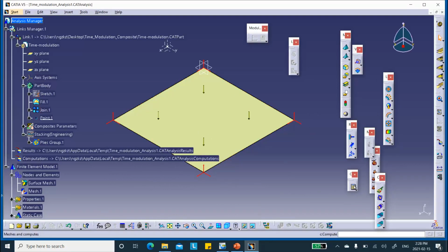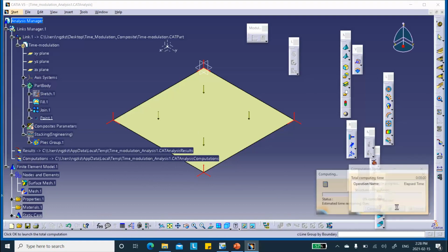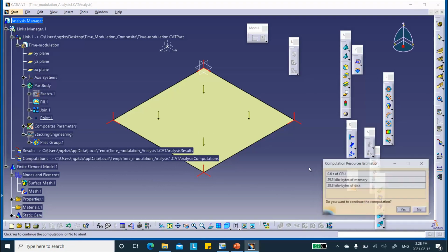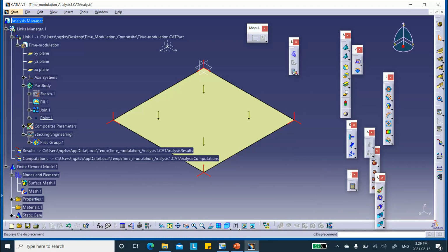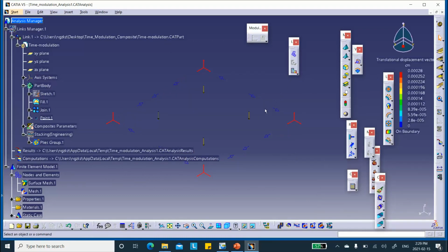If I did everything right and run this thing, it's going to give you a deflection of this under static load of 100,000 Pascal. And it will run. You can look at the deflection. Now, you might say, oh, wait a minute, this doesn't look right. That's because I've used too few elements, and the scale was so big that you can't see them properly.